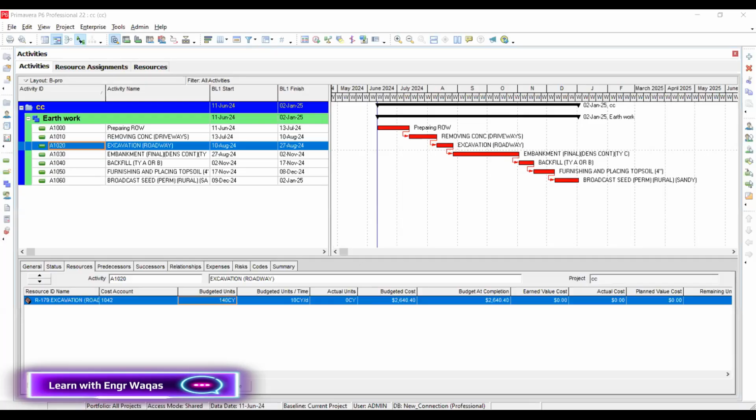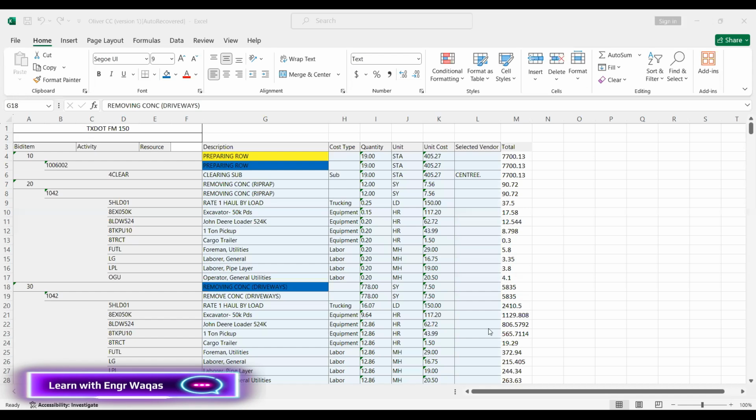And then if I want to track my activities under this category, I can define it over here. I want to track my activities under this vendor name, under this cost type: manpower, material, machinery. Primavera P6 is actually tracking all these things automatically. Don't worry about that. This cost type and these activity codes will be directly assigned to my activities. So how to do that?